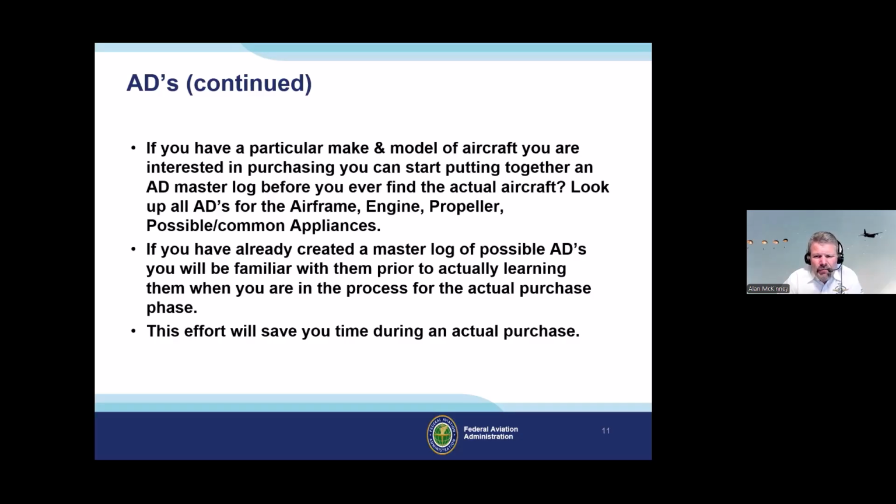Is there a requirement to have a master log of ADs? There's no regulatory requirement. The regulatory requirement is 91.417 to make a logbook entry. But you can see how helpful a master log is.